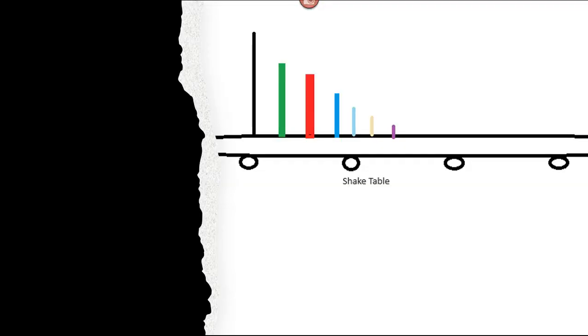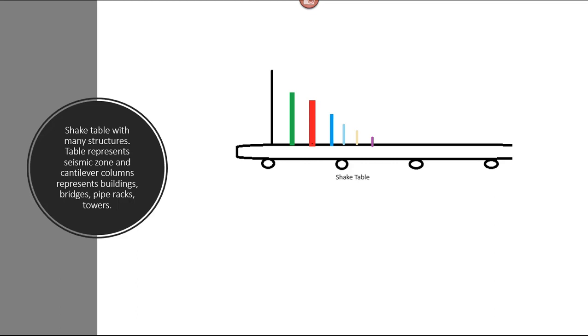Now, response spectrum analysis procedure is used to analyze your structures for seismic events. So basically, for doing this type of analysis, first you need to provide computer programs with a response spectrum curve. I want to give you some background about how these curves are produced. First of all, you may have to use codes such as ASCE 7 to come up with these response spectrum curves.